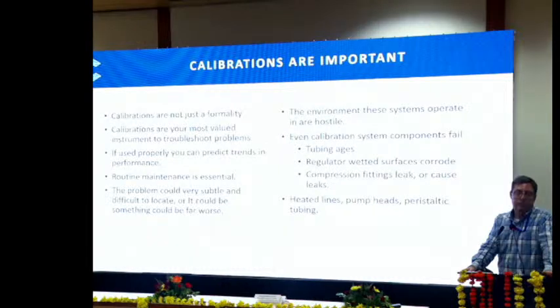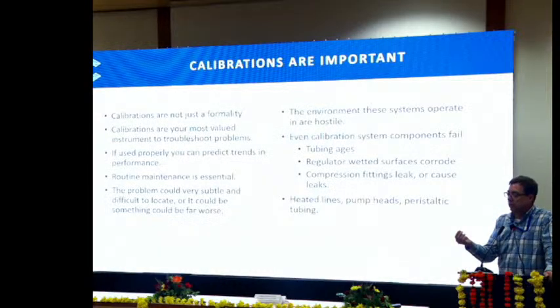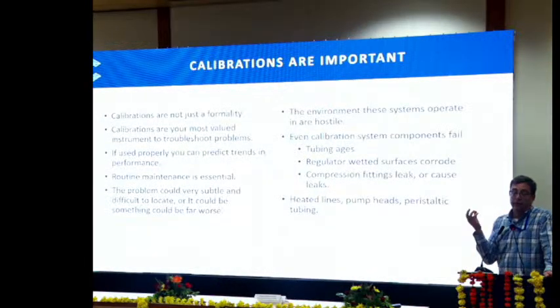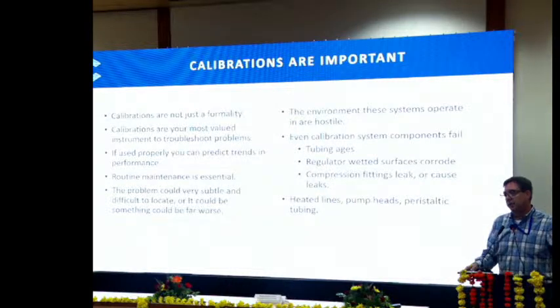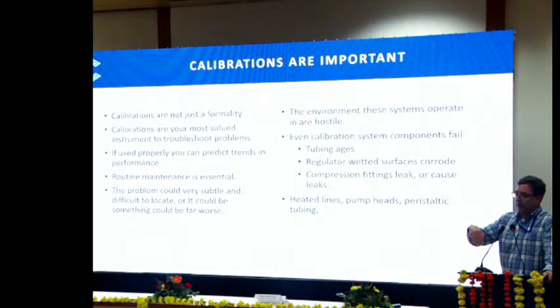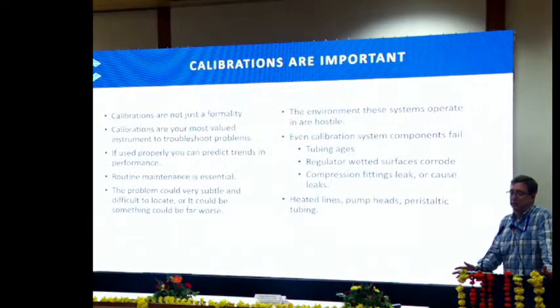Like I suggested previously, if you have material buildup, you can get salts that build up in your sample lines. You can get excess particulate. You may think that your filter for your extractive CEMS is seated properly, and you could get very, very fine particulate breaking through there and getting into your line. That can cause SO2 to scrub. It can cause interference with some NOx.